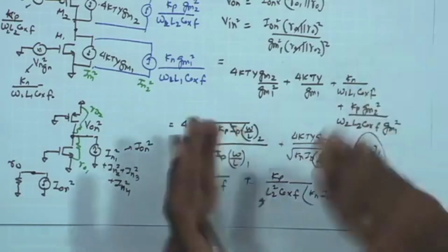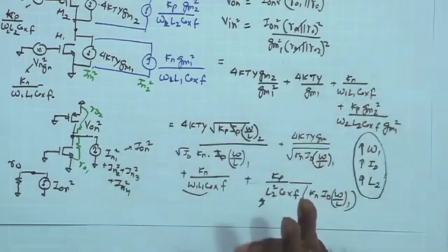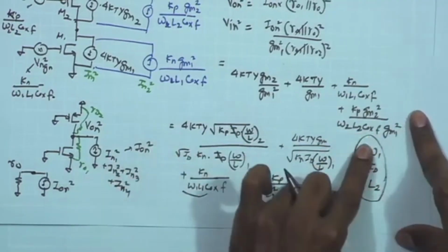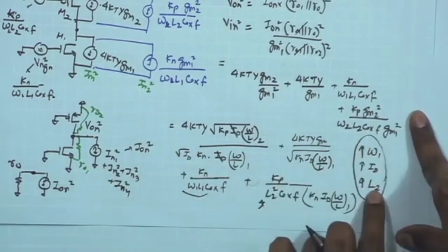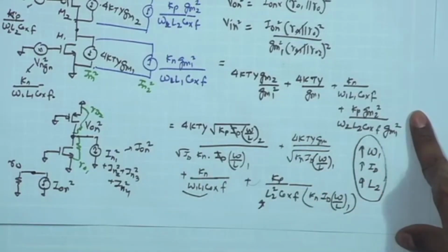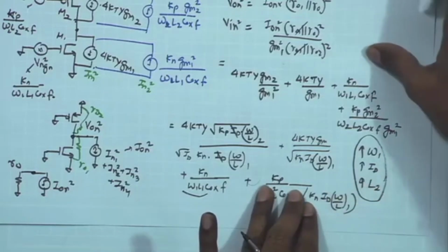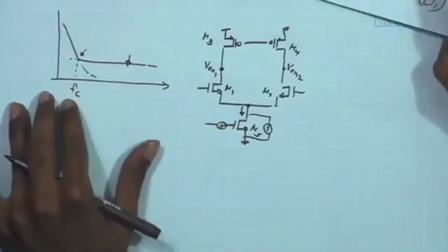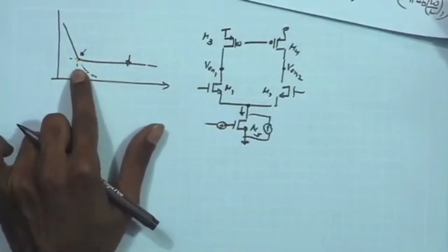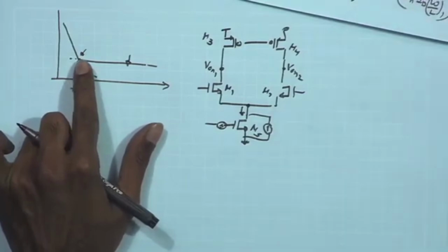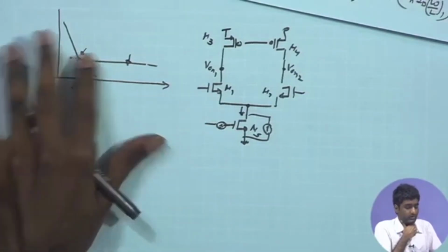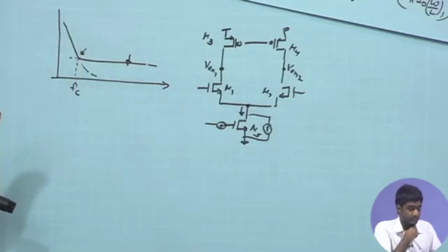We would like the upper cutoff frequency to be at least a few hundreds of hertz to kilohertz, and we must meet all those constraints while we are sizing these input devices and the channel length of the load device larger. So, if we just rely on those two considerations, we will definitely have conflict with our bandwidth requirement, and also with our power budget for the overall amplifier. So, we need to look into some other techniques through which we can possibly have a better solution for this 1/f noise.